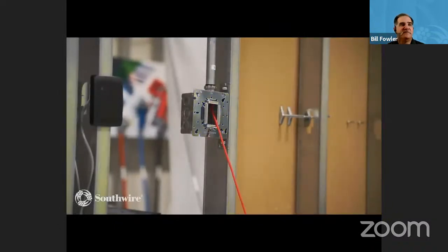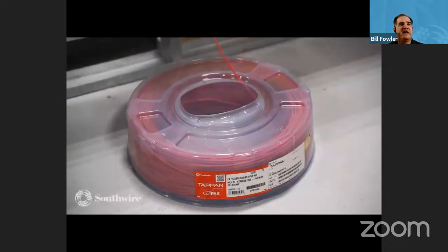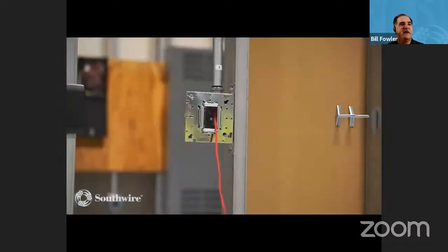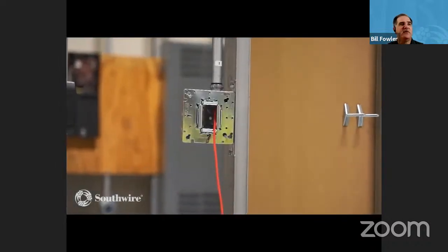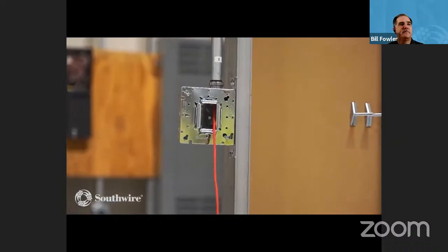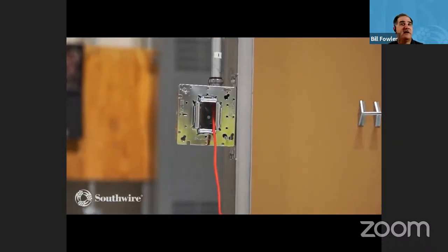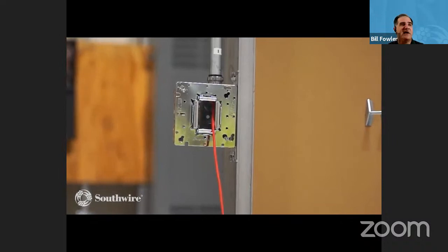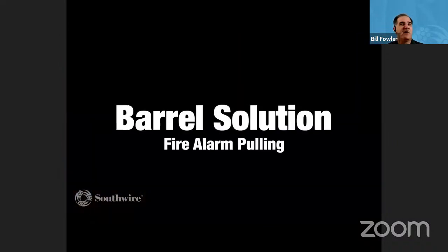Starts, person walks away, then it's pulling itself. I love that little roller panel so it keeps the cable from dragging, because again, we're typically dealing with soft jacketed cable, low voltage cables, easy to tear, easy to rip. That's why we see a limit of 25 pounds on pulling. The good thing about the XD1 and a drill with a selector guide on it, you can turn it down so you won't exceed that 25 pounds. It'll clutch out when you hit that 25-pound mark. You won't damage the cable.